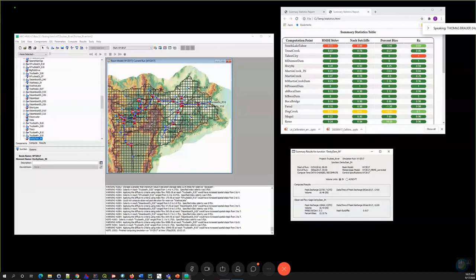I know I've had to do that on a continuous study. We had to go in and reevaluate the volume for the biggest event on record. I was doing modeling in the Russian River, and the biggest event on record was the 1964 event. Data in 1964 is not great. So yeah, we looked around at neighboring gauges, figured out what they were doing, things like that, and justified what we did. But that's just the caveat. You can try to massage it, but you definitely put it in your report. Talk about it.